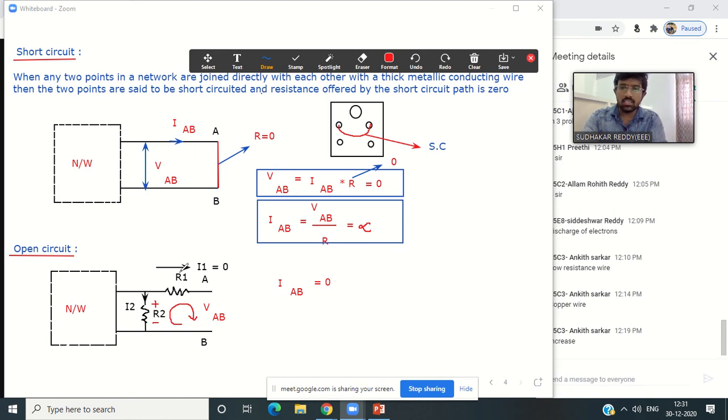Is there any voltage drop across resistor R1? No, right? Good. So the current value is 0 now, because there is no voltage drop. No need to consider it. And similarly, assume the polarity for this VAB is plus minus. Now, can you write the KVL equation starting from R2 in the clockwise direction? What is the KVL equation?